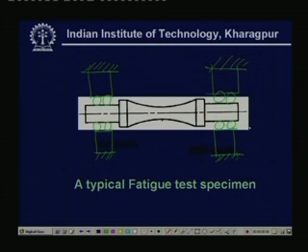Okay. Now, you understand this specimen is mounted on pairs of bearings, so that by an external motor you can give a rotation, and by some means we apply a load, if I say, and so corresponding to load F i we can compute the stress sigma i, and in the experiment, corresponding to this load F i, the number of cycles, as we have just seen in an earlier slide, the number of rotations required for the failure of the material is recorded.